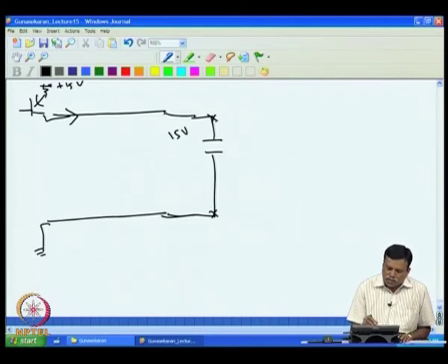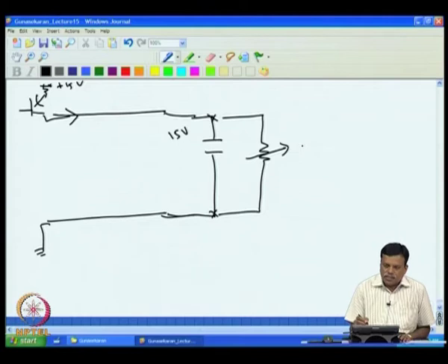Now, I have to use this for powering the various devices. So, if I connect this to a resistance here, and if this resistance changes, then depending upon this load, the voltage across this will be varying, because if the load resistance is small, then most of the current is going here, and only a small current is going to the capacitor. Even then, as the time passes the voltage will increase, and then more current will flow across this.